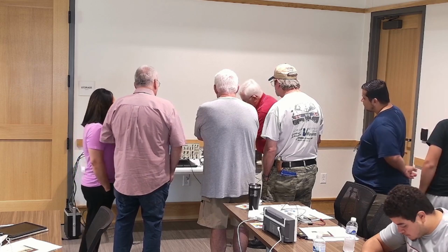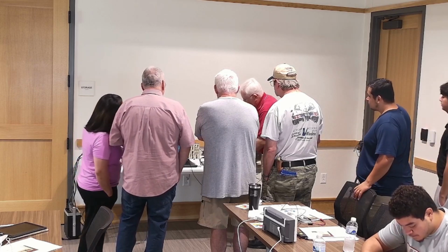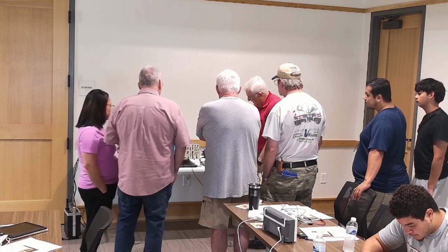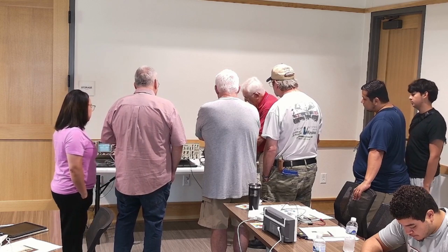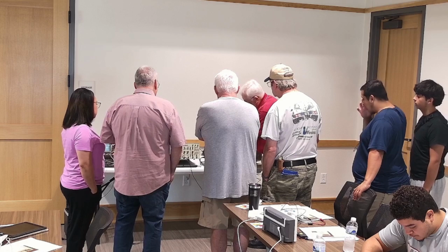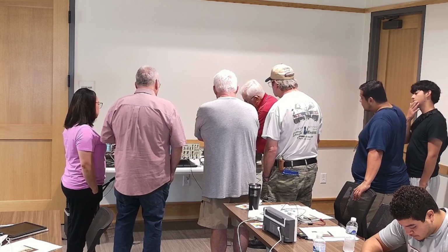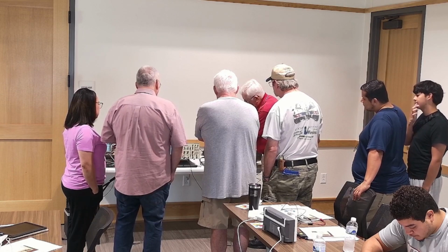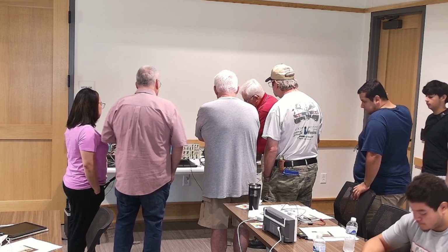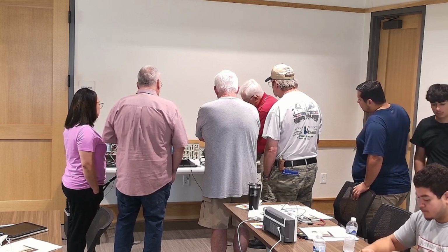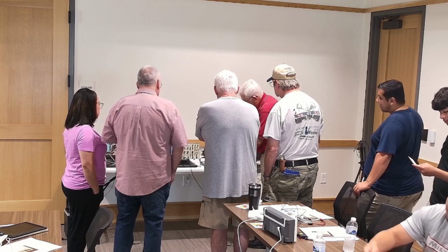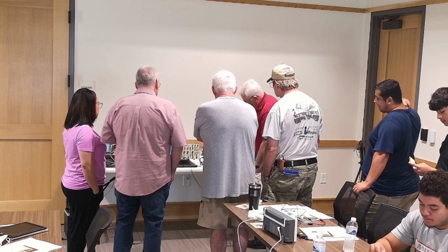It would just cover up, from here to there, one scale, or the scope would downshift to a different voltage reading to give you a bigger picture. I'm doing it automatically, but you can control this value with these knobs here. I can change the voltage values: 2 volts per division, 5 volts, 10 volts per division, and it'll go all the way down to microvolts, 20 microvolts. Back to there. So you can play around with those things.